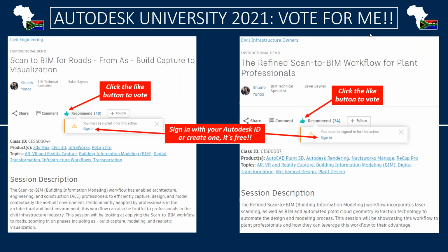So decorations are the things that you would normally model in 3D in Infraworks itself for purely visualization, and that is it. If you wanted to take those things into an assembly, you would probably need to create it using the standard assembly tools in Civil 3D, or use the Subassembly Composer, which there's a split on. Some people find it very difficult, some people kind of get it and it works for them. I'm not saying which way I sway, but it's really, really powerful. I think you just need to wrap your head around the Subassembly Composer and you can do a lot of amazing stuff. It's a good question.